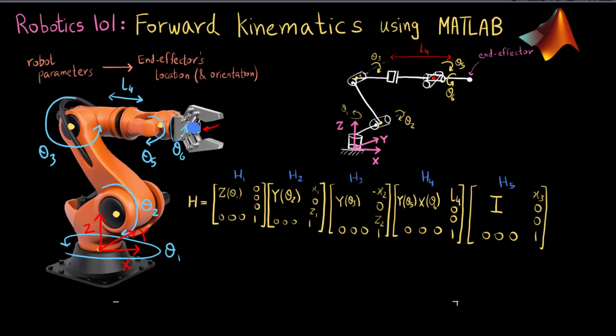And one thing that I forgot to mention beforehand is that whenever you are doing the forward kinematics, you do the forward kinematics at the zero configuration of the robot. What I mean by the zero configuration, or the home configuration, let me write it out. So the zero configuration, also known as the home configuration, is when we assume that all the robot parameters are at 0 degrees or zero lengths, right?